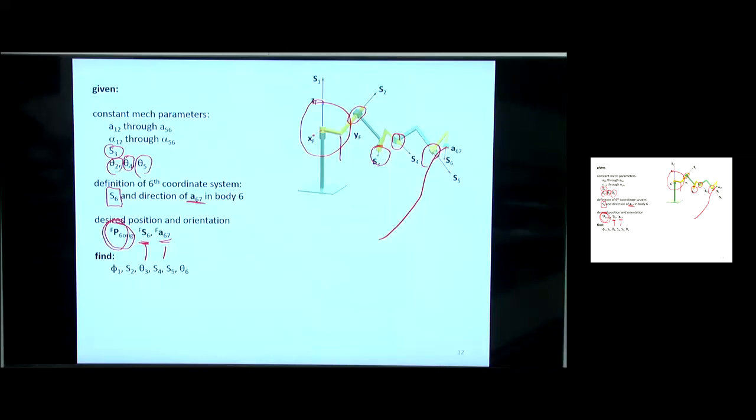So basically, I'm given the position and orientation. Find those 6 joint parameters: 3 angles, 3 distances. So this will be our first actual reverse analysis where everything's coming together, right? Based on all this given information, we're going to close the loop. And when we close the loop, we're going to find that we have a 1 degree of freedom closed loop mechanism where we're going to know theta 7 is one of the closed loop parameters, and then we're going to knock that thing out. So it'll go pretty easy.